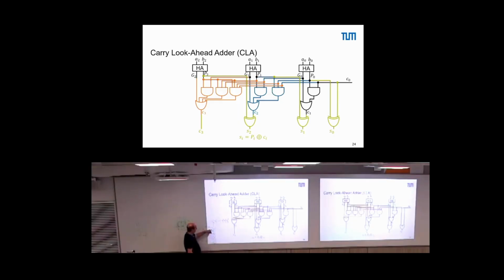At some point, if all those are maybe conducting, you have here still some voltage drops, and you're no longer able with this one here to switch, because your VDS, so the drain source voltage, becomes too low, the share that you have. So effectively, you're limited in what you can build there.